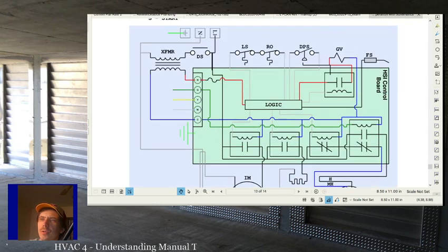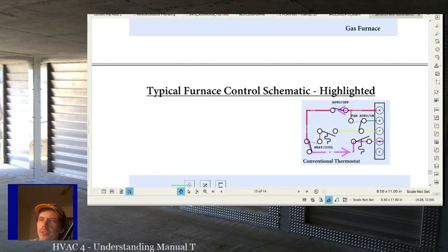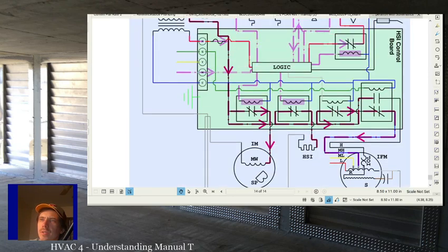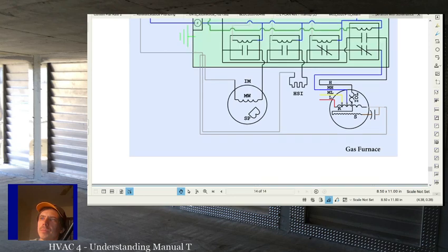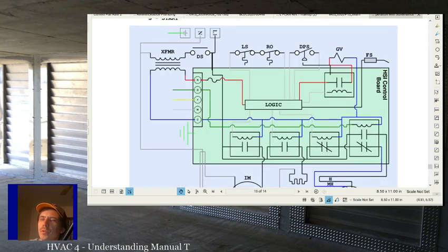And then if you guys look, when I sent you that link for the handouts and stuff, you've got a schematic here that you can look over that will give you an idea of how it's usually hooked up to a board. As a matter of fact, I really need to do one of these with the universal control, but if you look at the infrared heater one, that's a good universal picture of a universal, Honeywell style furnace control, hot surface ignition control.